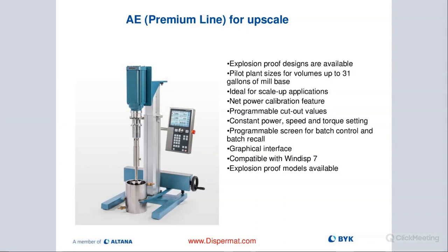And then when you're running your product, there will be no influence of the machine itself, because obviously, it needs energy to rotate the blade even without product. It has to apply torque to move the shaft. And by doing a net power calibration, we are factoring out those variables so that it's really only strictly related to your product.